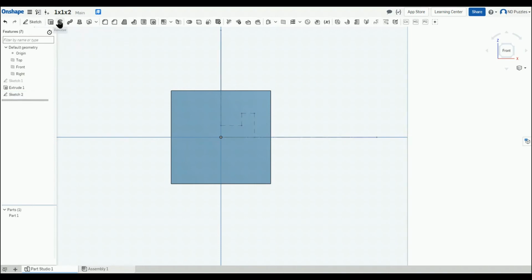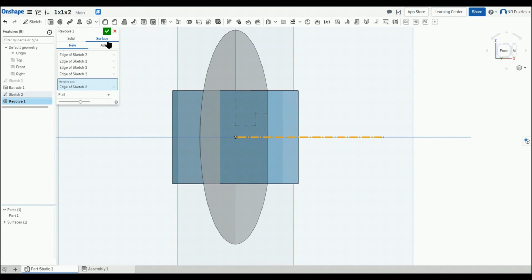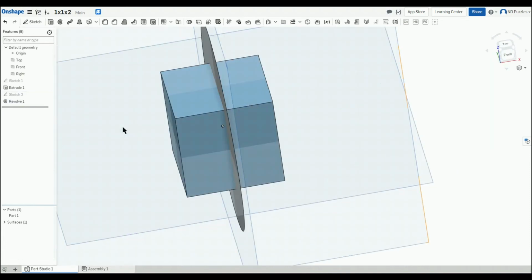Make sure that you see this horizontal icon before left clicking. Press exit to exit the line tool. Now choose the line tool again and just follow my moves. Make sure that every line is either horizontal or vertical. The dimensions don't matter right now. It is just important that you get the basic shape of the hook.